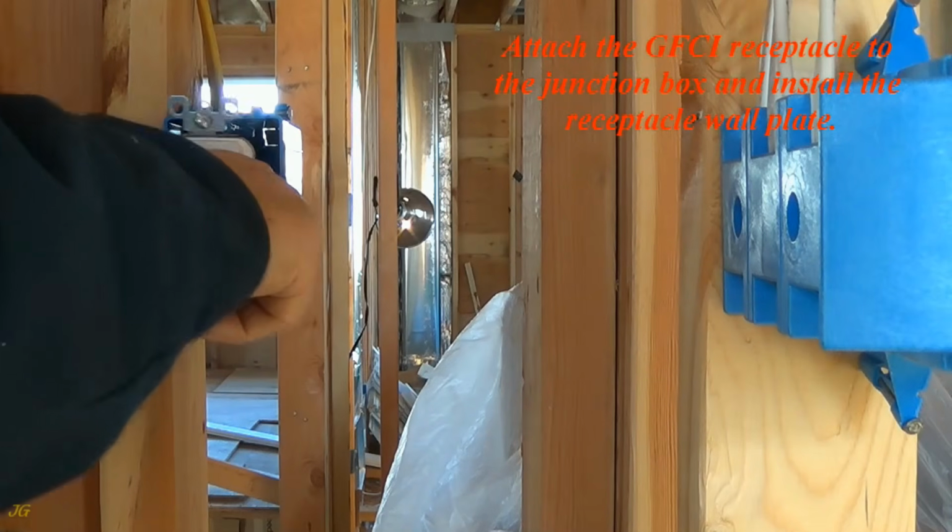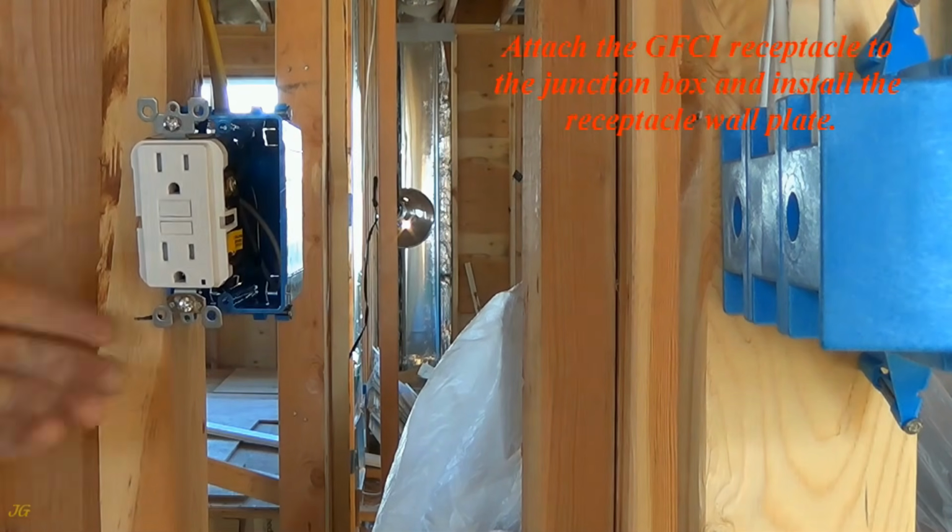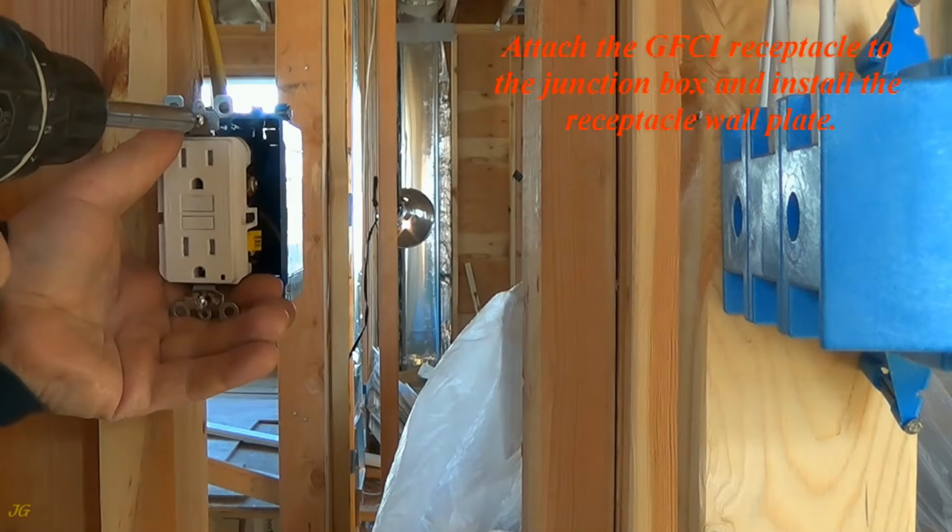Attach the GFCI receptacle to the junction box and install the receptacle wall plate.